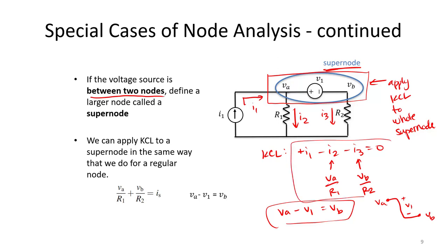So notice, if I use these two equations, I would be able to proceed with node analysis like normal. If I knew what those current sources, voltage sources, and resistors were, I would be able to solve for VA and VB. So if you see a supernode, you should be happy because that also gives you a very big hint about how you could approach that node analysis question.